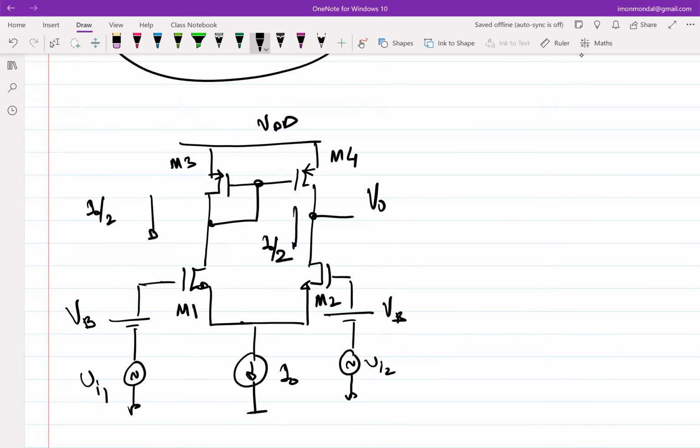Correct. So what he is saying is that, for some reason, maybe I want output from this node, and I don't want a diode connection at that node. So we can follow the same argument and do this. Nothing is stopping you. It's basically which arm is the mirroring arm and which arm is the mirrored arm, because the current is getting supplied from the bottom. We can do that. Okay, fine. If there are no questions, let's move into the analysis.